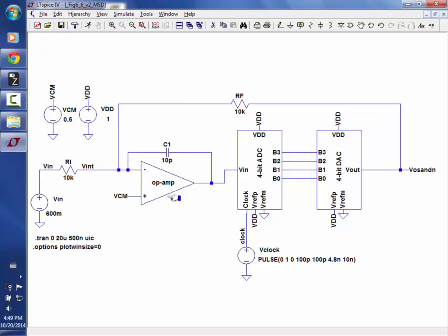Now this has negative feedback because the forward path has a minus sign in it. So if you push a current in here, the output goes low. That drives these bits low, which drives this low, which then pulls the current out here. So you get negative feedback. The issue is when we plot this signal and this signal, it's going to be inverted. So our transfer function from V out to V in is going to have a gain of -1. Does everybody follow that? Are there any questions on what I did there?